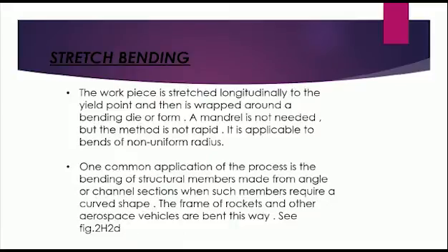So the next topic is stretch bending. Stretch bending is a part of metal forming where the metal is bent or stretched to create perfectly shaped automotive parts. A machine called a stretch press usually performs this process, shaping multiple different types of metal. When used in manufacturing, stretch bending helps to create automotive parts. One common application for this process is bending of structural members made from angle or channel sections when such members require a curved shape.